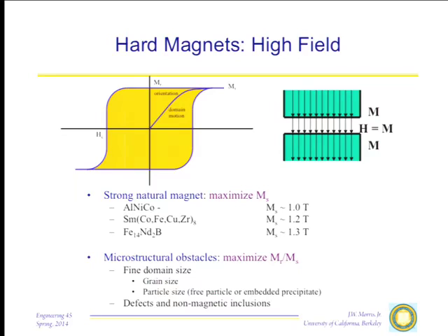One of the problems with these things, which kind of killed the eyeglass market, I could see it happening, but they wanted to fight anyway, is that neodymium iron boron is really unstable. It corrodes like crazy in air. So if you want to do something like a sunglass attachment, it works fine until you scratch the little surface and then it's gone.